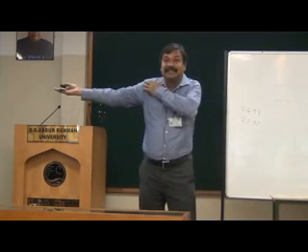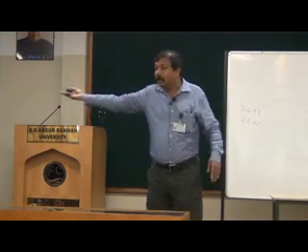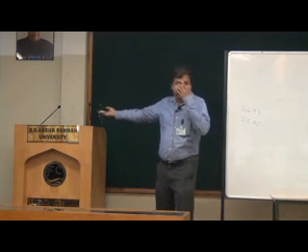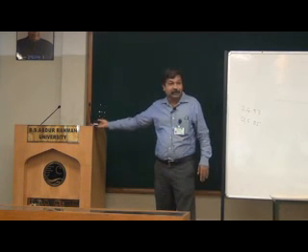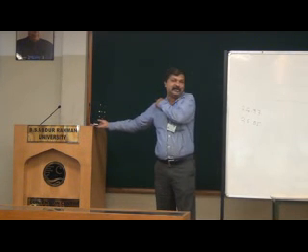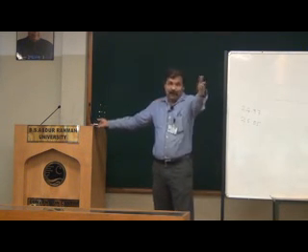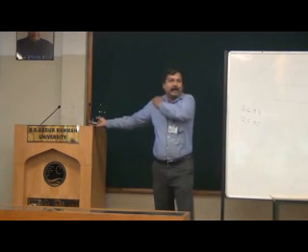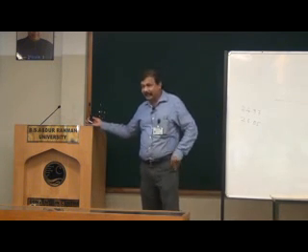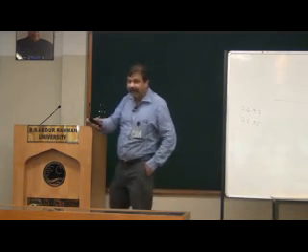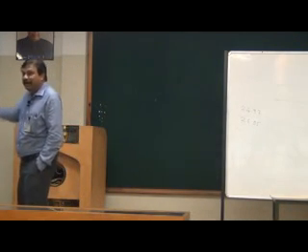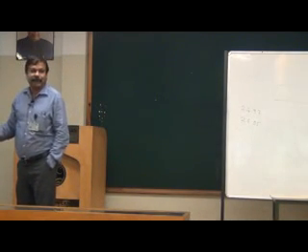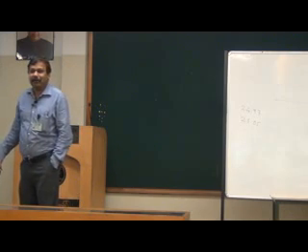At this position, this is a cantilever beam. On the other hand, when I rest it here, it is a simply supported beam. You can find out the support reactions, and then find out that the force acting at my joint is much lower when I could rest it like this. Similarly, but please believe me, a drill bit is a cantilever. It cannot become a simply supported beam.